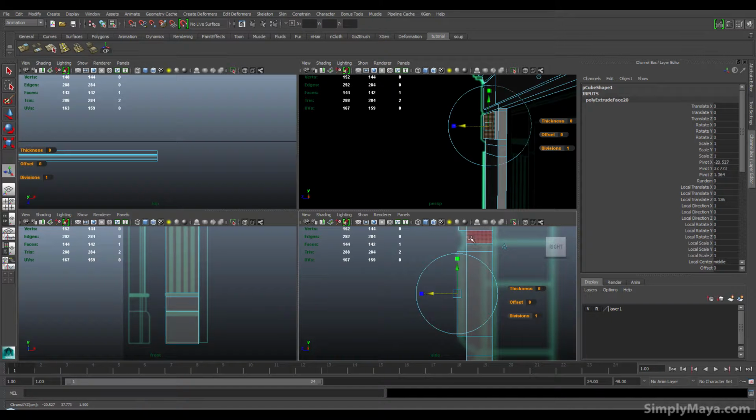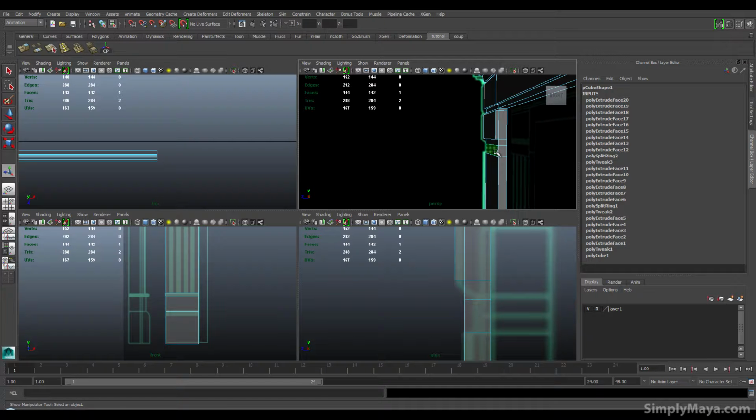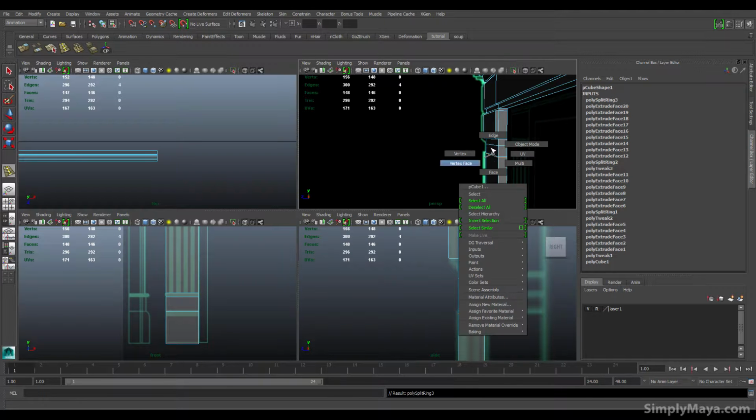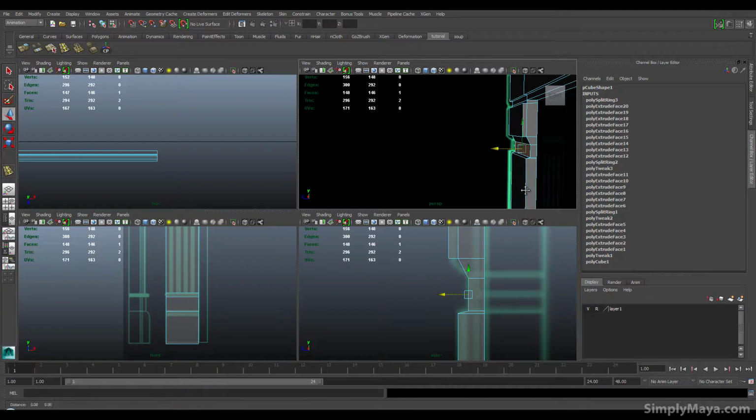And we'll worry about these curves inwards after we've got the main geometry done. Okay, and then we've got a curve downwards here, but that will be fine. We'll need to move this one inwards, which in order to help me create the curve and everything else, I'll actually just put an edge loop in here, because that will stop it deforming all this geometry under there. Select the face, and rather than extrude, I'll just push it backwards. Okay, and that gives me this kind of cut here and this more radical slope here, which is pretty much what I'm looking for.